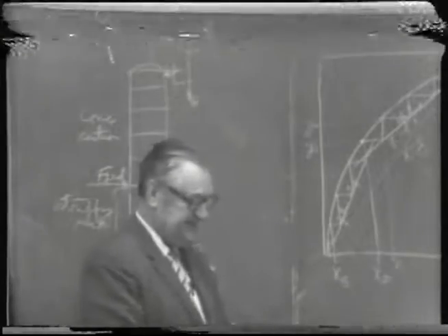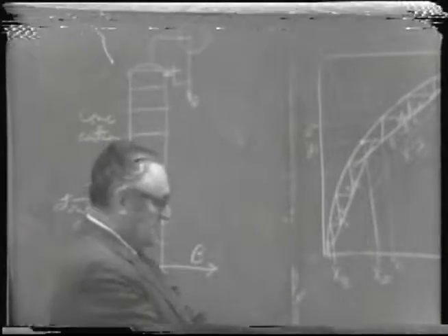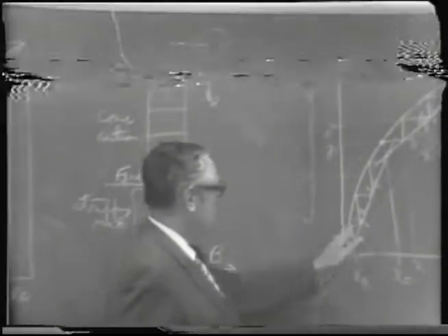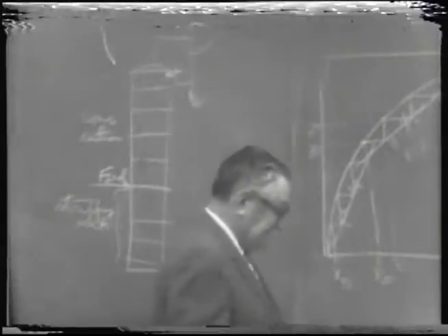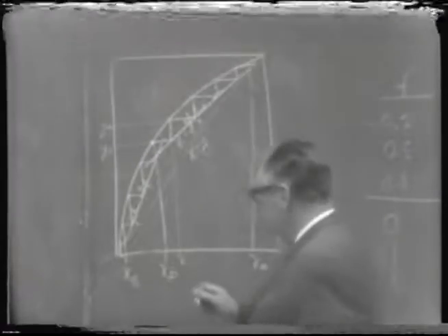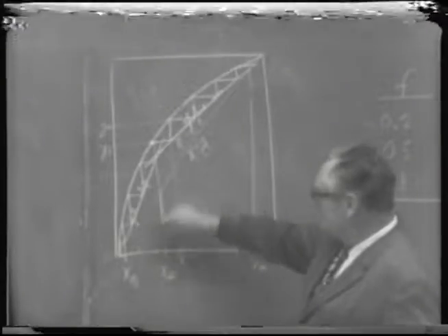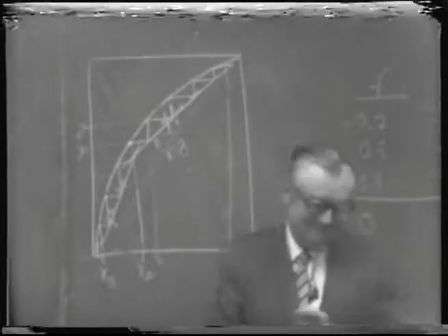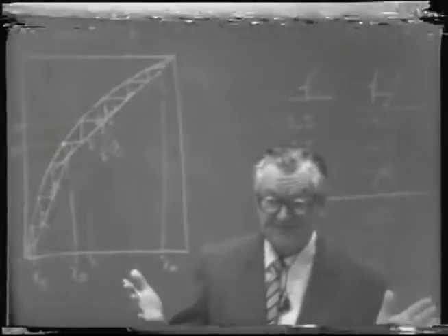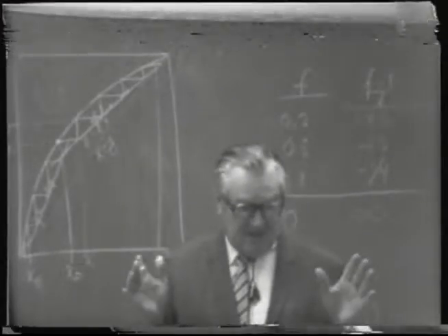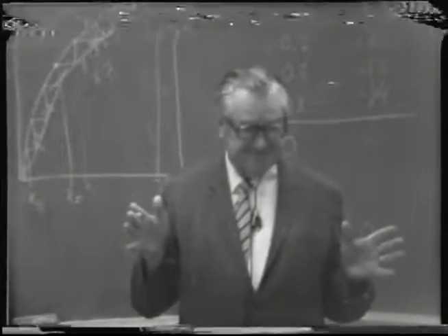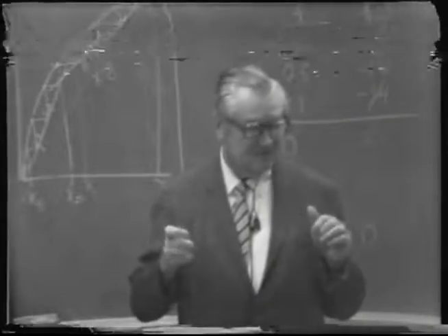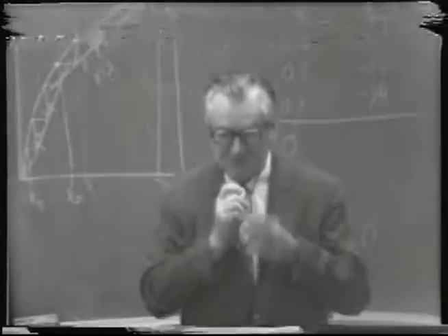Now, next time we will go into how we quantitatively locate these lines, so we can actually, in application, either calculate the number of stages required in the stripping section and the concentrating section to effect a given separation, or in the reverse process, for a given particular piece of distilling equipment, we can determine what the composition would be under various conditions where you have a fixed number of steps to work with.